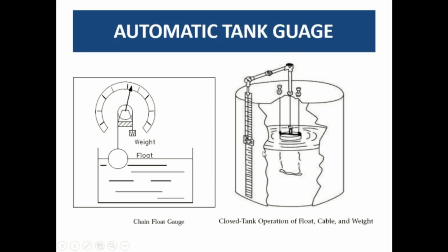So in response, ultimately you will get the wrong reading. If you have attached the transmitter as well, you will get wrong readings as well, because the displacer is again attached to this pointer, and once the whole assembly gets stuck due to uncleanliness of your chain, ultimately your reading will come out wrong.